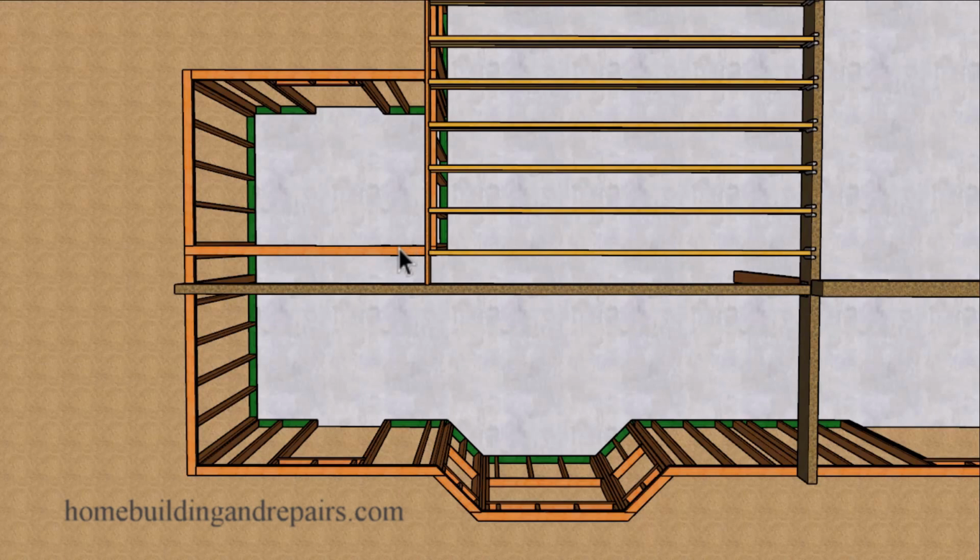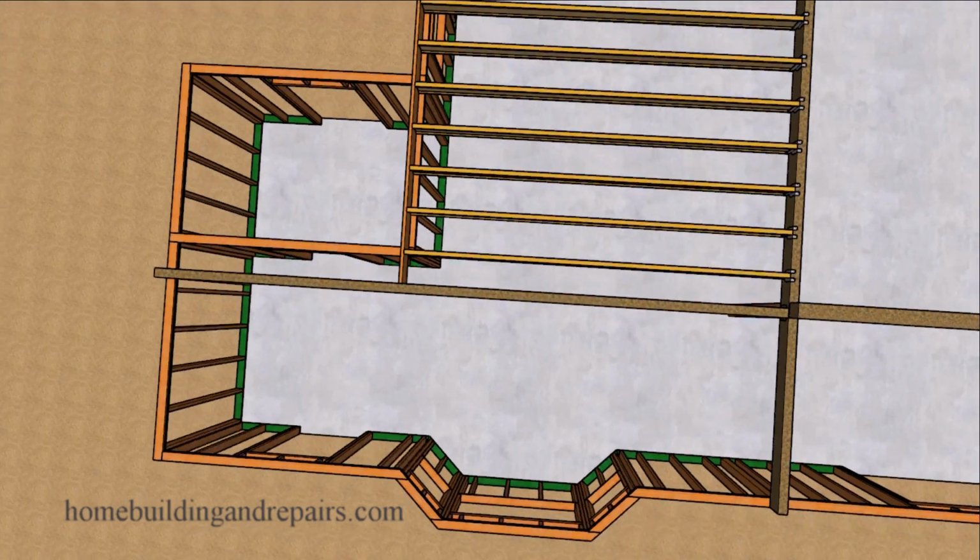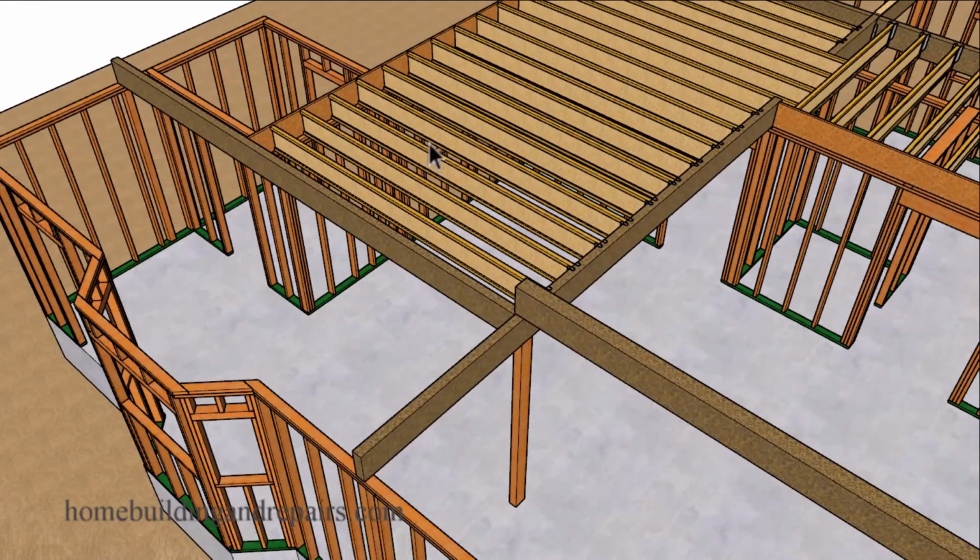However, you might be able to move the wall and have it sit under the beam, and then simply put a structural footing in the floor foundation to transfer that load down to the ground, like we have over here and over here. So you can get a pretty good idea how the beams are supported to create open spaces in the lower floor.